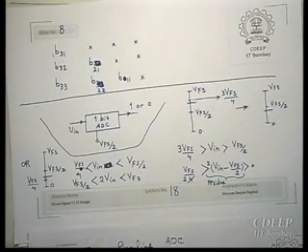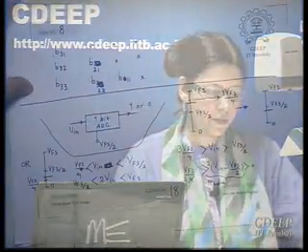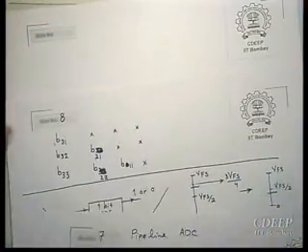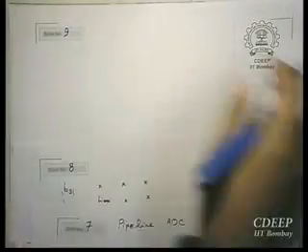So in a pipeline ADC, if you want to use similar stages, say a 1 bit ADC for all stages, you need to calculate the residue first and then scale it up, and therefore again you use the 1 bit ADC with the full scale. V ref by 2 will be your reference level. So every stage of the pipeline should do this job.